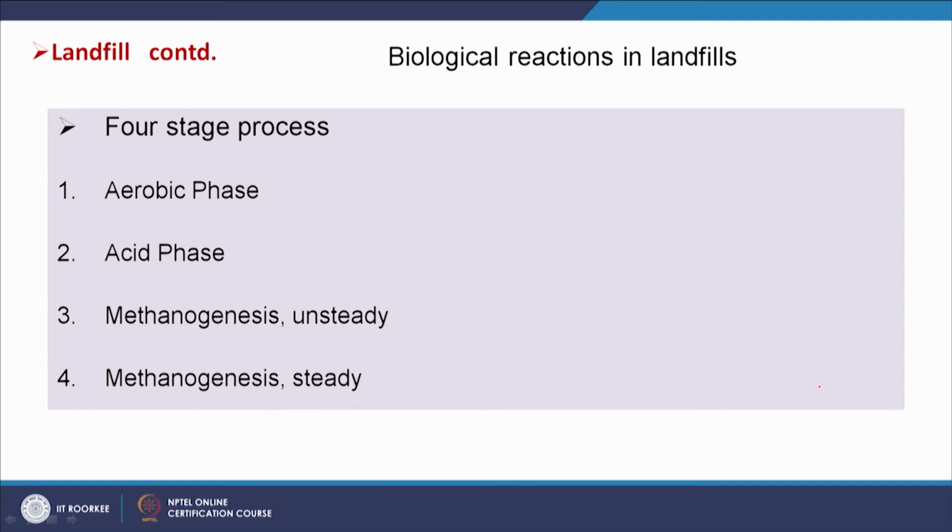So, this is an example of the restoration of a landfill, and the different types of reactions which can take place in landfills are similar to anaerobic digestion reactions: the aerobic phase, the acidic phase, and then the methanogenesis phase, unsteady and steady. At the top part there is the possibility of oxygen, so aerobic reaction can also take place. As we go inside, when the depth increases, the acidic phase reacts, then after the acidic phase, methanogenesis phase reactions take place. This is unsteady and then steady state.